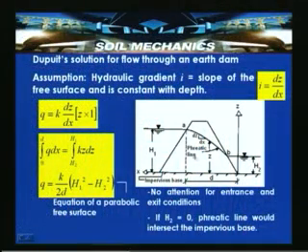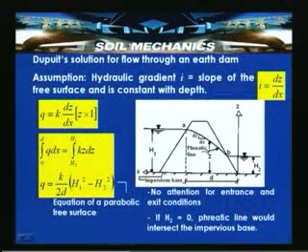So, if the flow is treated as a two dimensional problem, q is equal to k into dz by dx into z into 1. dz by dx is nothing but the slope of that particular phreatic surface. Z is this depth here and 1 is the perimeter length of the dam. Here k is the coefficient of permeability, which is assumed isotropic because the dam is constructed with a homogeneous material. So, it can be assumed that kx is equal to kz is equal to k.